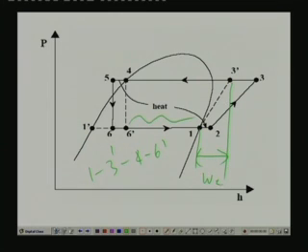Okay. Let me point out at this point, and this I have already discussed in the earlier lectures. When you are using a liquid suction heat exchanger, what is happening is the compressor inlet is entering into the superheated region. This is your superheated region. So, you can see that point 2 is in the superheated region, whereas with the SSS cycle the compressor inlet is a saturated vapor. Okay. So, this will have a bearing on the performance, which we shall see shortly.